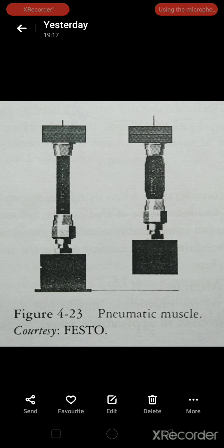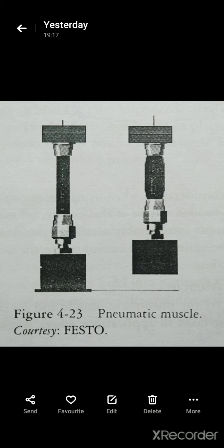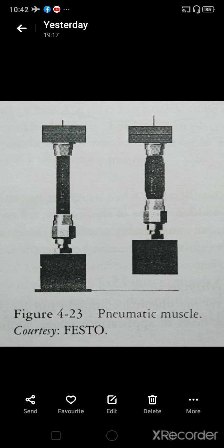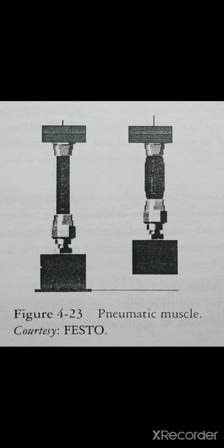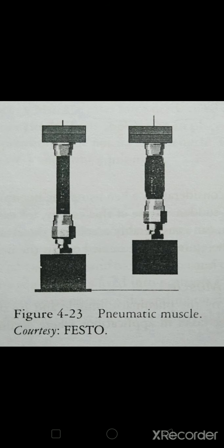Apart from this, you should also take care of the safety criteria for the application. Generally, safety also needs to be taken into consideration when using the pneumatic muscle, right? A muscle under pressure has enormous energy potential. A sudden release of this energy, for example caused by bursting of the reinforced tubing due to incorrect use, can considerably accelerate the attached component of the muscle.